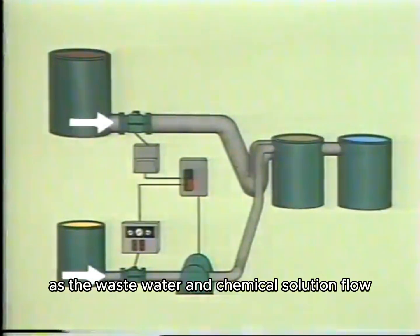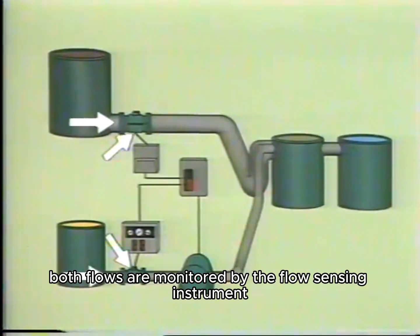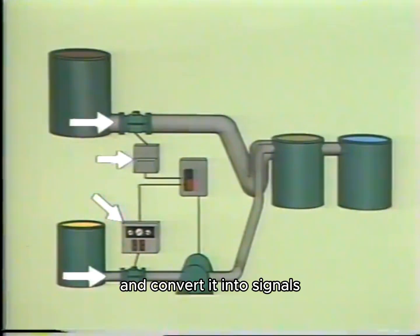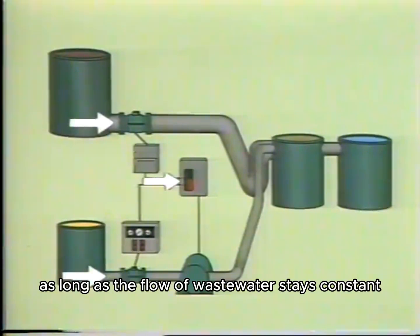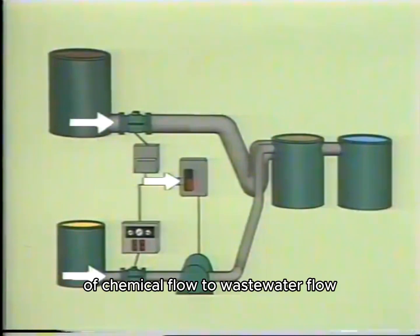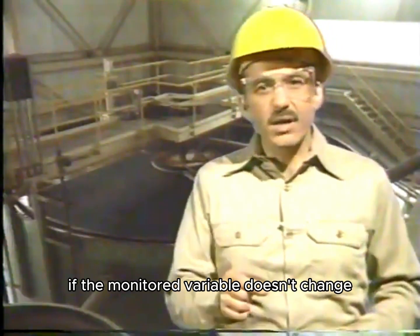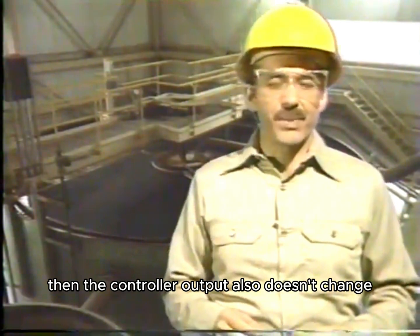As the wastewater and chemical solution flow into the mixing tank, both flows are monitored by the flow sensing instruments. The transmitters measure the flow-related information and convert it into signals. These signals are sent to the controller. As long as the flow of wastewater stays constant, the controller will determine that the ratio of chemical flow to wastewater flow is being maintained. That's usually true of most control loops. If the monitored variable doesn't change, then the controller output also doesn't change.